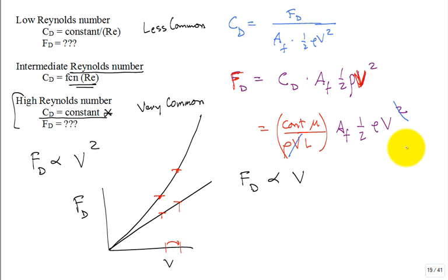This is true for a lot of things. Let's say the drag force on an automobile. It's going 30 miles an hour, and then you decide, I know the speed limit's 30, but I'm going to go 35. I'm in a hurry. Does it increase the drag on your automobile when you increase the speed from 30 to 35? Yes, it does. You're doing 80, and you say, well, I'm in West Texas, 80 is the speed limit, but I really want to go faster, and I'm now going to boost it up to 85. Only a 5 mile an hour increase. But the drag went up a lot more going from 80 to 85 than from 30 to 35, because it's proportional to v squared.